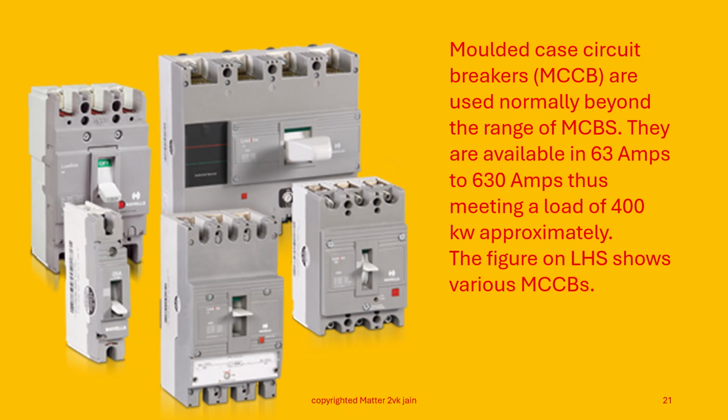Different types of MCCBs are shown in this slide. This is a single phase. This is a three-phase configuration, three-phase and neutral category, and some other categories. These are available from 63 amperes to 630 amperes, thus meeting a load of 400 kilowatt approximately.